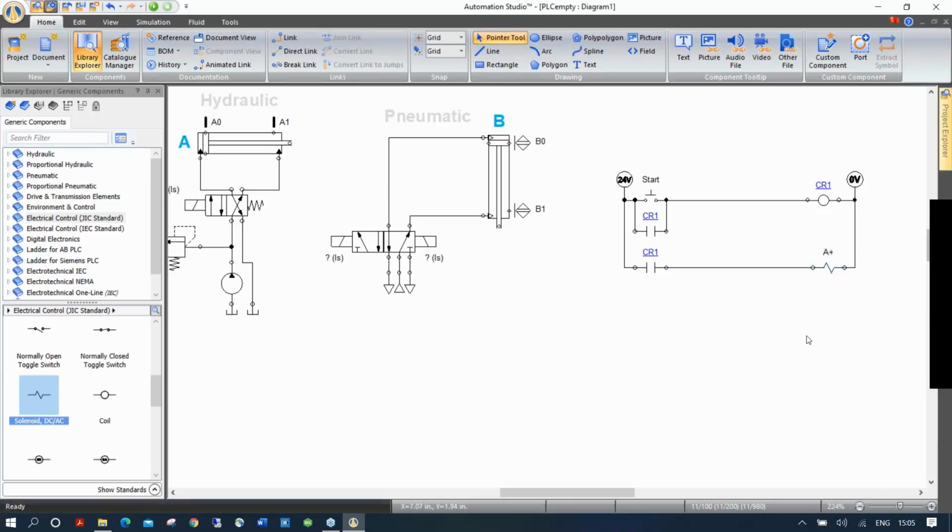so I can actually move this wherever I want to realign the circuit. So then A is going to come out, and I need to latch this because you see it's a spring return. So if I cut the signal, it's just going to go back right away. So I need to latch it so it goes to the end, and that's why I latched my button here. And then when I reach A1, I want B to extend.